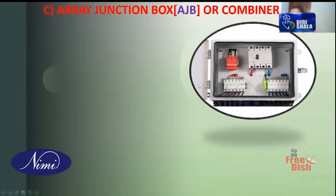So as you all know, the solar PV system comprises of two types of supply, AC and DC. From solar panel up to the input of the inverter, it is DC. From output of the inverter up to the load, it is AC. So in between, we are using the junction box. So this is called a DC junction box, or you can call it a combiner box, or an array junction box, AJB.